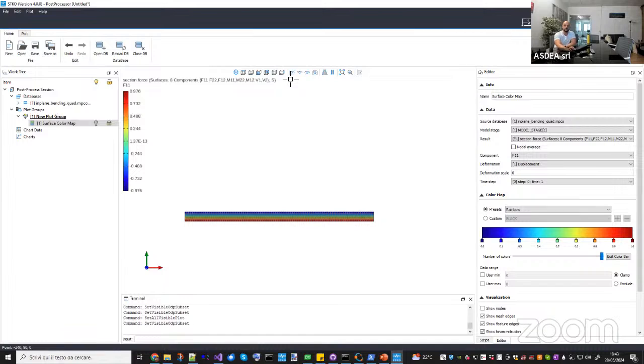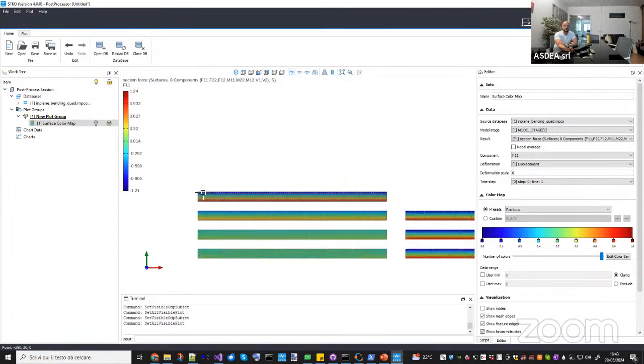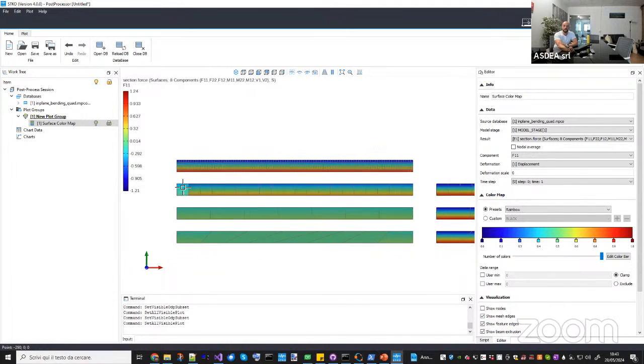Okay, so you need a lot of them, because I often see people using just 3 elements on a slab or on a wall. That's never going to work, okay? So either you need a special formulation, or if you have a displacement-based formulation, do some tests because it needs a quite fine mesh. Now, what's the problem? This one is fine if the mesh is regular, but now you will see how the solution deteriorates if you add mesh distortion.